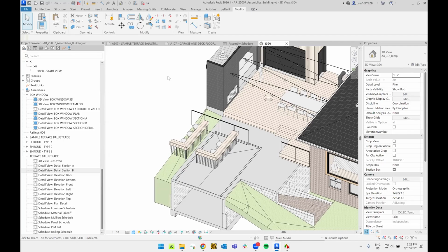So they're best for teasing apart live portions of your project model. And in terms of an assembly versus families versus project repository, use a family where you can. They're not mutually exclusive, obviously, but a project repository is still better for things that repeat. So assemblies are good for one-offs, but if we're going to be using this, let's say, box window, for instance, around the project, then you'd be looking to do that in a repository space, like a kitchen type or something like that.